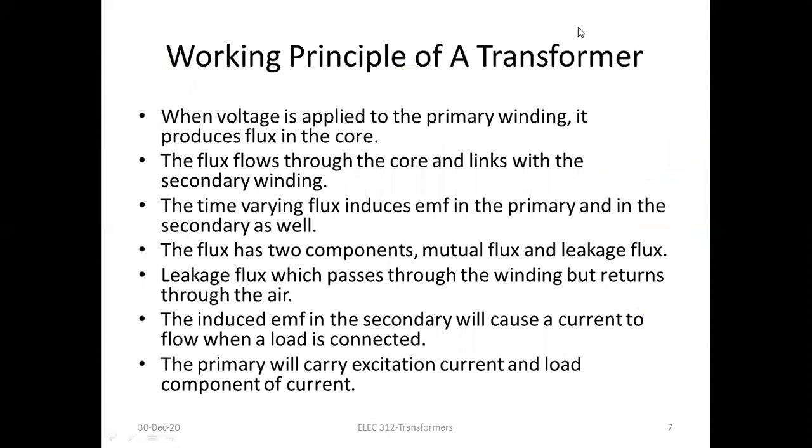So this is the principle of working of a transformer. Let us see some more examples. When voltage is applied to the primary winding, it produces flux in the core. The flux flows through the core and links both the windings. These two things I have explained in the previous slide also. The time varying flux induces EMF in the primary and in the secondary.